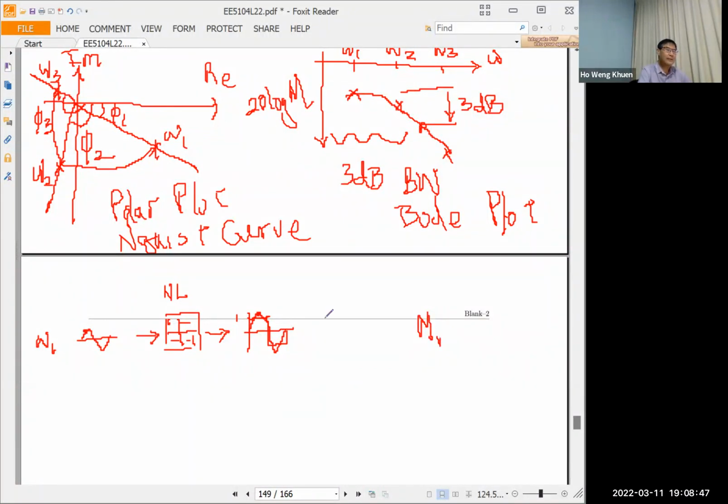Then after that, since you pretend to see a sine wave, even though it is really a square wave, you also compare the sine wave with this sine wave on the oscilloscope and say you have a lag of phi 1. This is at omega 1.